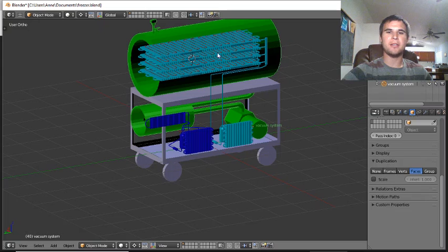The capacity, the size of the chamber, having it big, assuming that you can pull it down to vacuum, it'll actually help us, because the small amount of gas that escapes, that sublimates out of our product, will be absorbed by the greater volume of the vacuum chamber. A tiny, tiny vacuum chamber really quickly can get overwhelmed, and then the pump gets overwhelmed, not because the pump doesn't have the capacity, but because your little tiny chamber just pressurizes too quickly from the off-gassing.